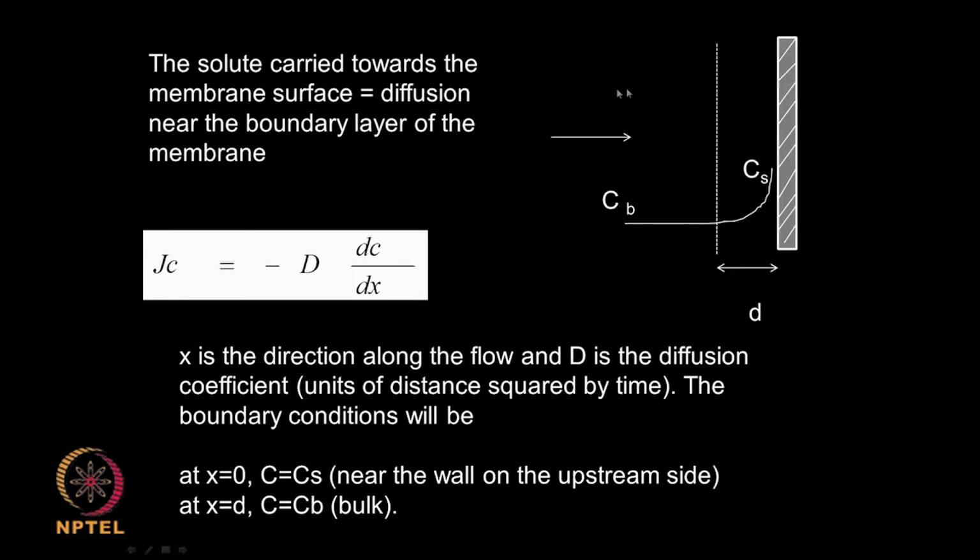One important point which we need to understand is called concentration polarization. So, when I am doing a membrane operation, as the fluid moves in, this is the membrane material, this is downstream. Okay. So, the concentration of the solute keeps building up, and generally the concentration of the solute near the upstream wall is very high, much higher than the bulk. So, as the concentration keeps building up, that is called concentration polarization, the flow keeps going down, and after some time there is no flow at all of the liquid here because of the build up of this solute.